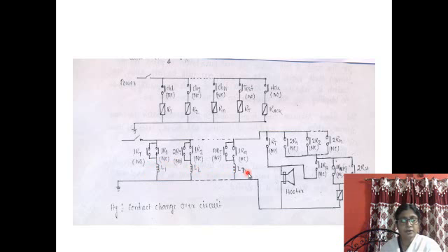Similarly, for all n number of channels, if there occurs any failure, even if multiple failures occur in different control loops, that will be detected by the corresponding lamps. Now the audio signal. How will this audio signal be produced? For all these channels, the relays R1, R2, Rn, for the visual signal there are contacts 1R1, 1R2, 1Rn, like that.